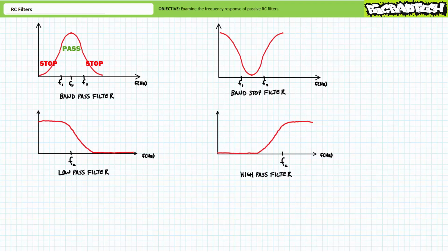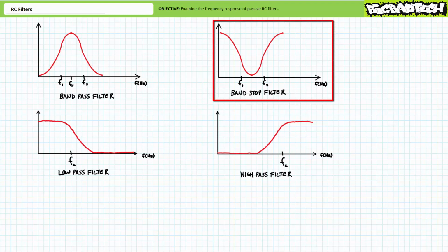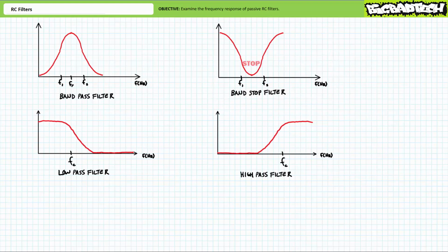The behavior of a band pass filter explains the title and vice versa. Frequencies inside a specific band are passed, hence the name band pass filter. Get it? Other types of filters exist, notably band reject or band stop filters, which are almost the exact opposite of band pass filters, where a band stop filter excludes or rejects frequencies inside a specific band, also defined by an F1 and F2, and they experience less output. Frequencies below F1 experience more output, as do frequencies above F2. As previously, the behavior of a band stop filter explains the title and vice versa. Frequencies inside a specified band are stopped or rejected, hence the name band stop filter.